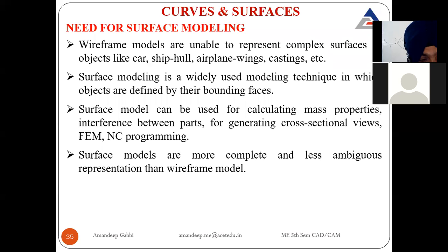Surface models are more complete and less ambiguous representations than the wireframe model. The confusion that exists when you are working in a wireframe model is eliminated in the case of a surface model. There is always confusion about which face is the front one, which is the rear one, and which line or point to pick when you are creating something on it. On a surface, it is clearly visible that this is the front surface and this is the rear surface.